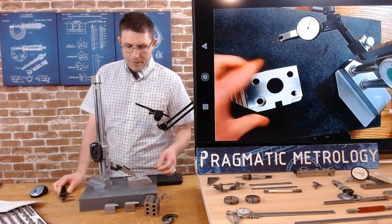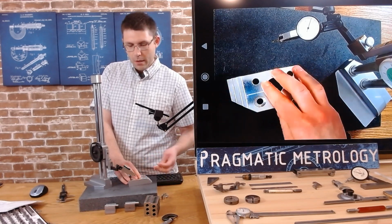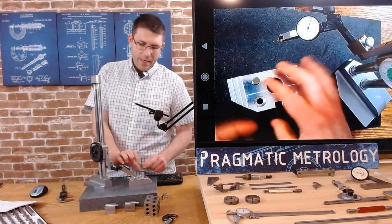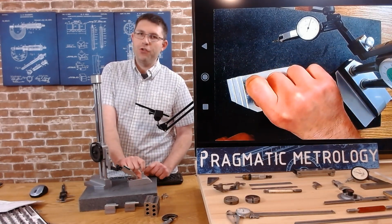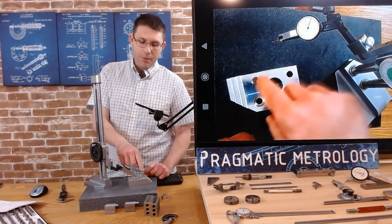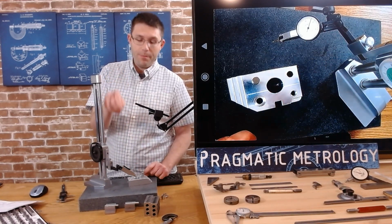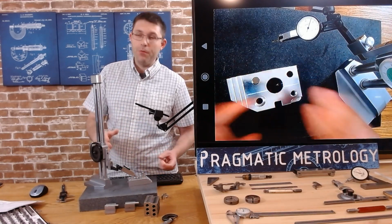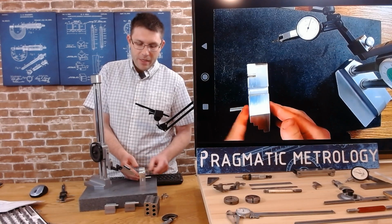So if I wanted to know the perpendicularity error of this hole and add that to my true position error, if my hole length is 1 inch, I want to measure a 1 inch travel on the pin as well. Now, if this pin were longer, let's say 4 or 5 inches, and I measured that entire 4 or 5 inch length of the pin sticking out, well, I'm going to get more and more error. But in reality, our hole is an inch long, so I'm going to use an inch long measurement with a pin.